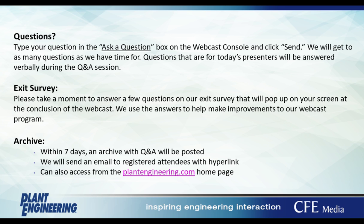Very good. We've got time for a couple more. For your step 3 that you noted in the presentation, can lockout tagout be done with a safety PLC? Yes and no. The PLC cannot really be locked out. So the safety PLC is really there to deal with safety while the machine or process is operating.